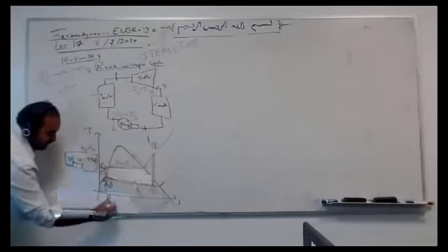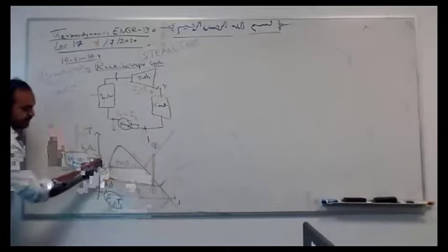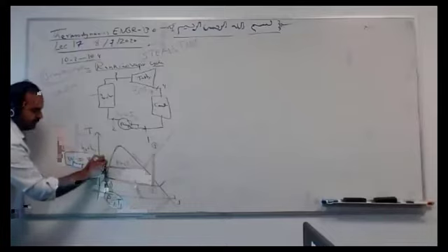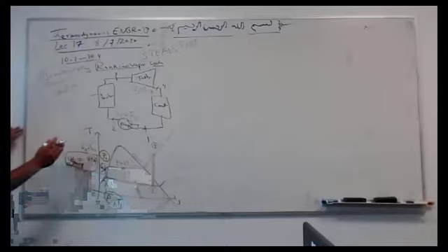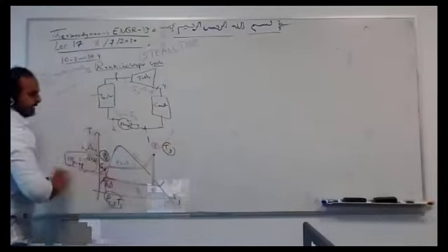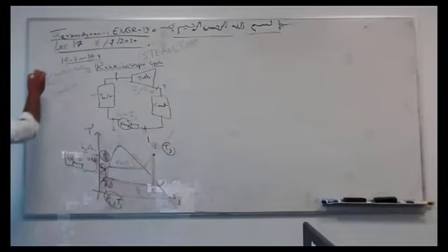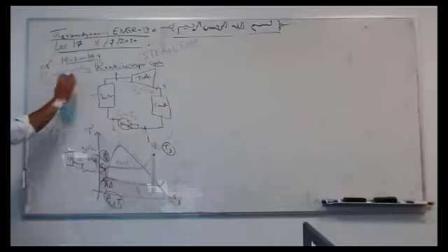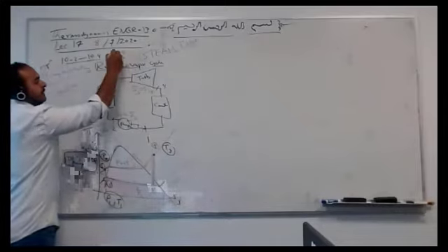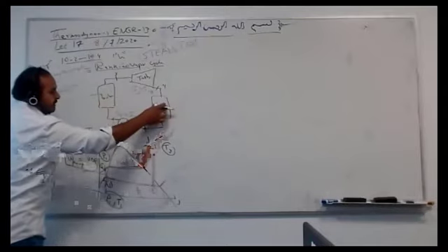So let's say I give you 4 independent pieces of information. Let's say I give you P1, T1. I give you, for example, the pressure ratio, so I implicitly give you P2. Let's say I give you, for example, T3 or the heat. I can get everything. Unlike Brayton, where I wanted temperature, here I want enthalpy. This is an open system.